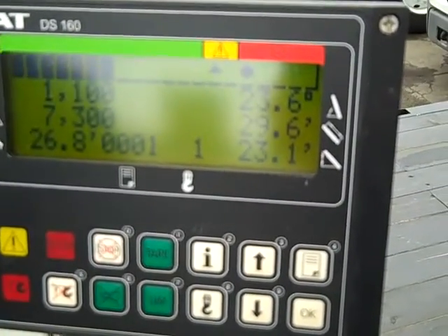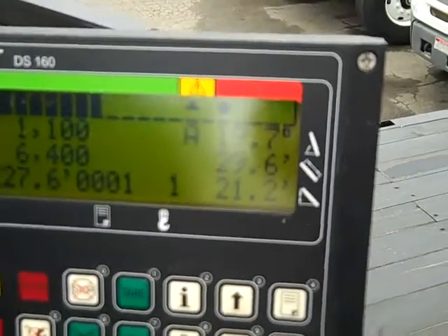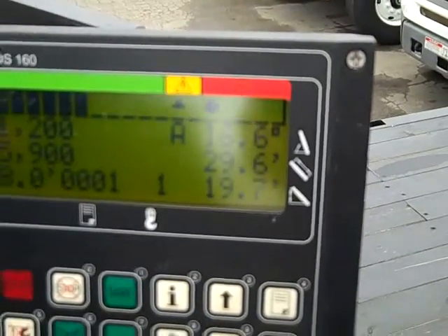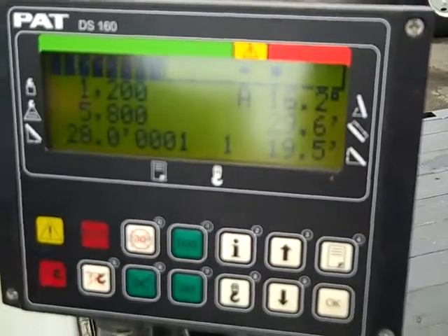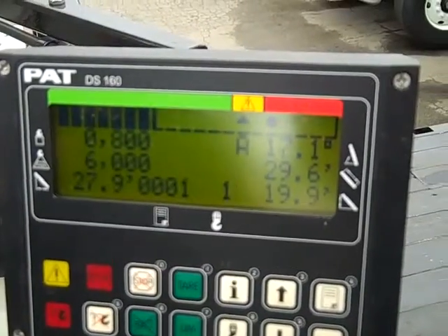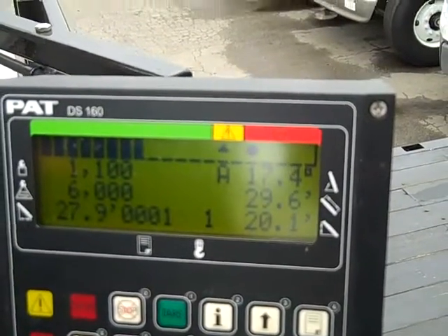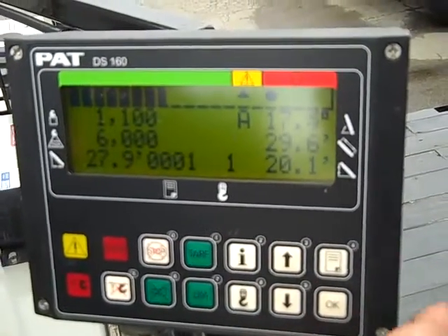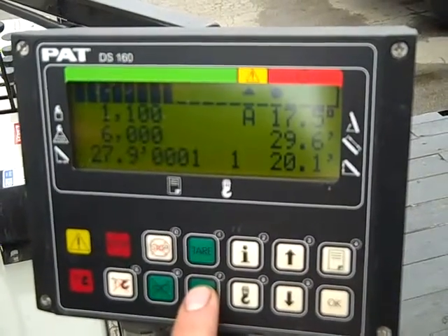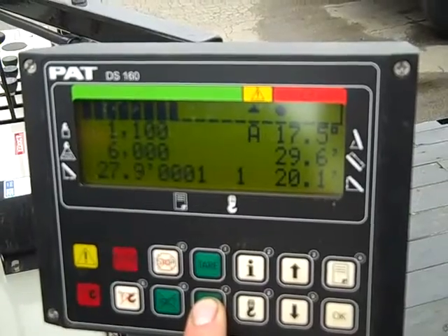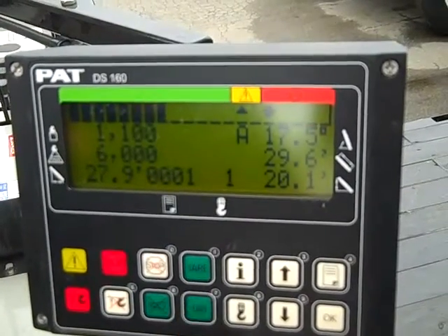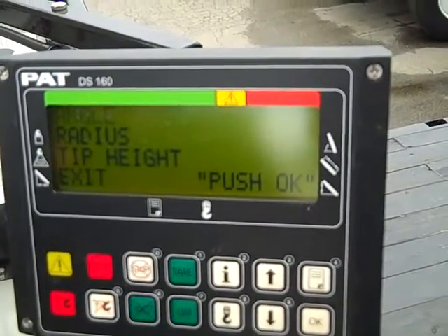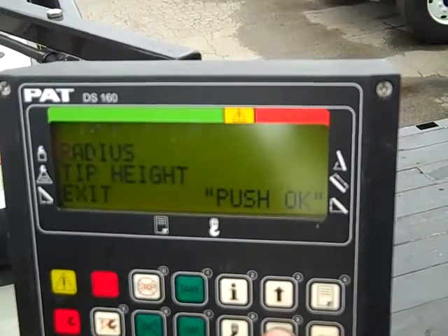The same would happen for a minimum angle going down. So once you go within the safe area, the alarm stops. Yes. What you are doing is creating an operation window that you would want to stay in. And is that only for boom up or boom down? No. If you go back to limits, that was your angle that we did.